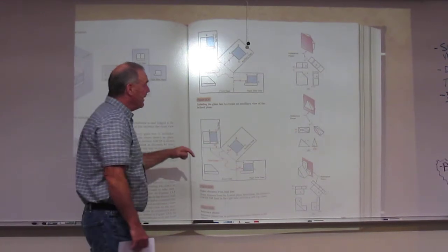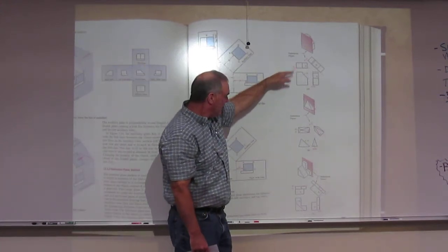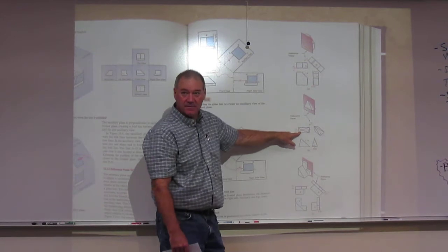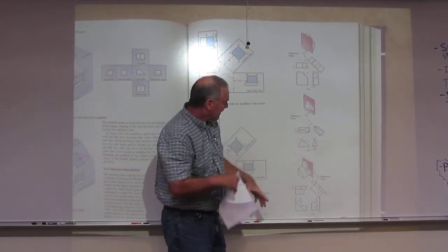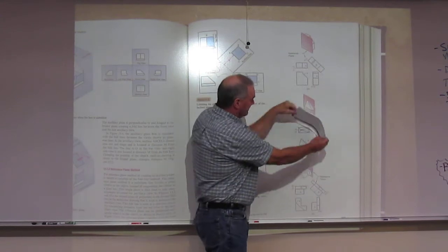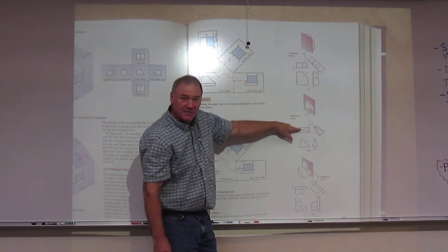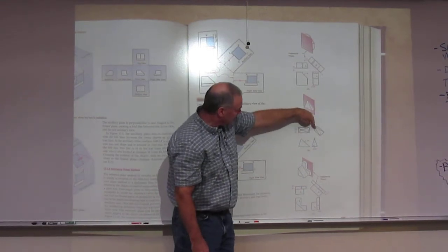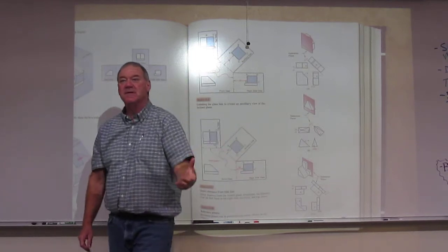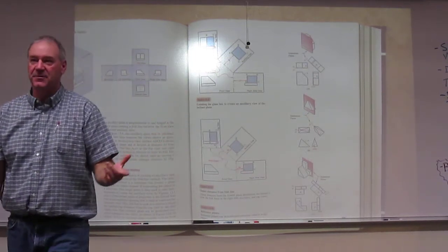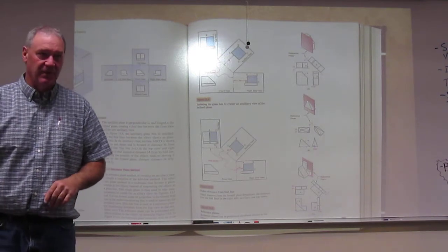We can also take this plane, and since we're just picking one, we can make an imaginary one, like in this instance. They put one right through the middle. So again, I'm seeing it on edge, on edge. Now, for me to build my auxiliary then, I can then just take this line, set it over here, and offset both ways, and I get all those dimensions at the same time for one measurement. So we're just picking a plane that is useful to us.